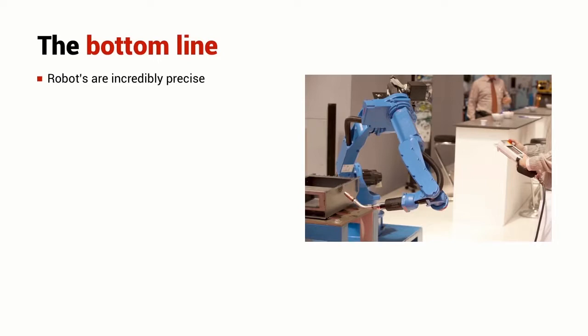There is a consequence for this traditional approach to robot positioning. For a start, we need to have very accurate sensors on each of the joints. The robot links need to be very accurately machined so that they reflect the kinematic model embedded in the software. The robot links also need to be very stiff so that as the robot changes its configuration, the links don't bend and deform under the influence of gravity.